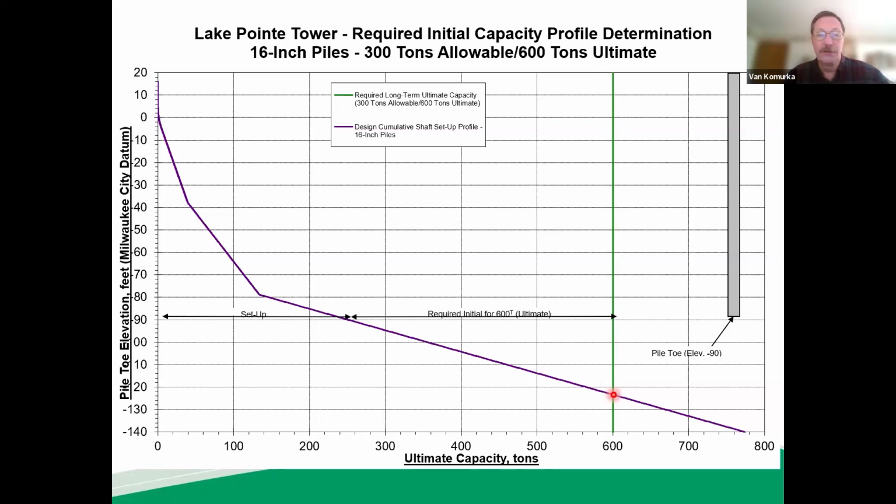And I've had this conversation with structural engineers. They'll call and say, I have an inspector in the field, and I thought we were putting in high capacity piles, and he or she is telling me that we only need 10 blows a foot when we get down to a certain depth. That can't be right, is it? And I somewhat facetiously respond, yeah, that's right. And if he'd driven another 10 feet, he wouldn't need any blows at all. That usually precipitates a meeting. That doesn't placate anyone. But you can see in this presentation how that comes about.